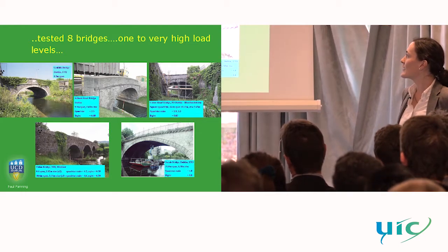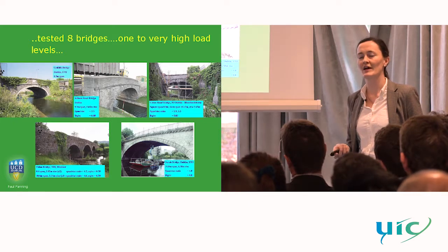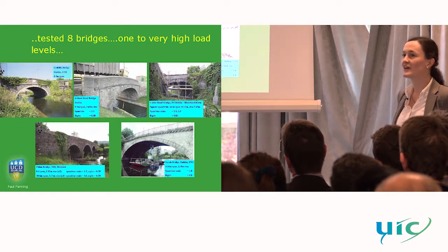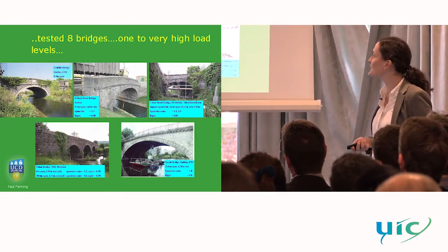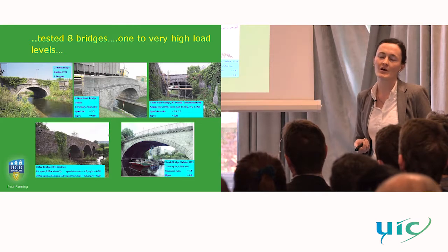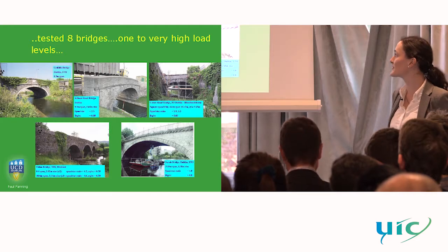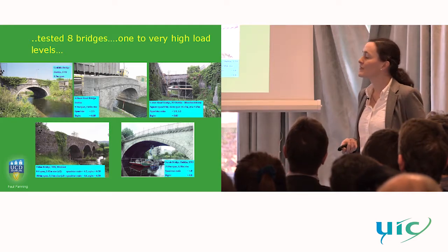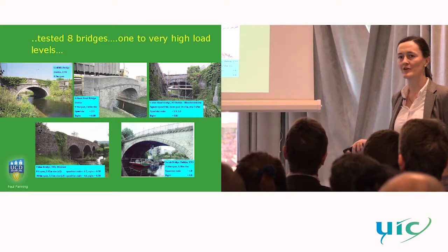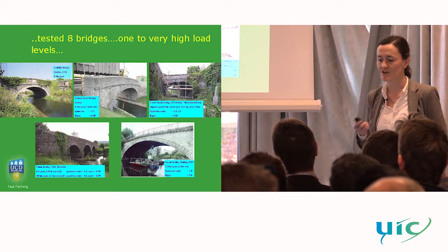So essentially, the three-dimensional modeling approach also needed three-dimensional data to try and validate it against. The majority of these structures were instrumented using LVDTs to get displacement measurements. And then for the UIC work that we did, we also instrumented with accelerometers. Again, I'll refer to that in tomorrow's presentation.